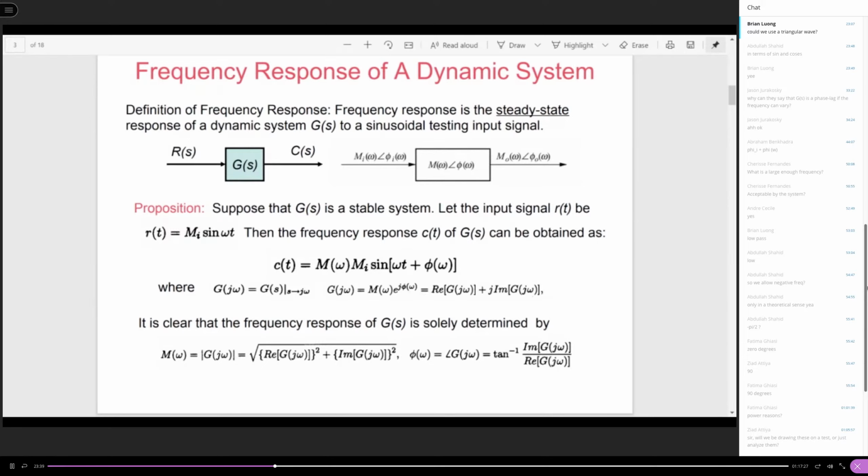The Fourier series analysis for a triangular wave turns it into a superposition of sines and cosines. So using a triangular wave is by nature equivalent to using a series of sine and cosine waves with different frequencies. Eventually, you can reduce the response to the triangular testing signal into the response to frequency oscillation signals.